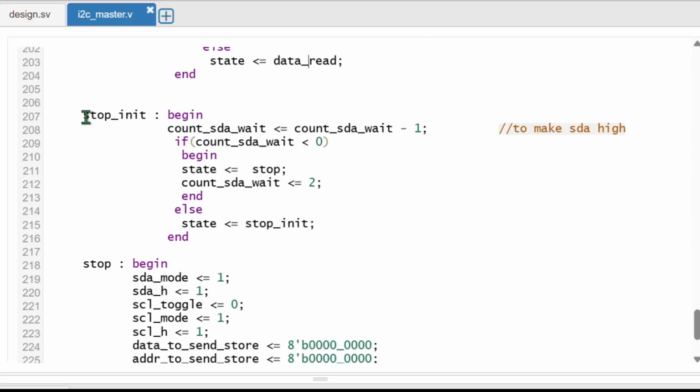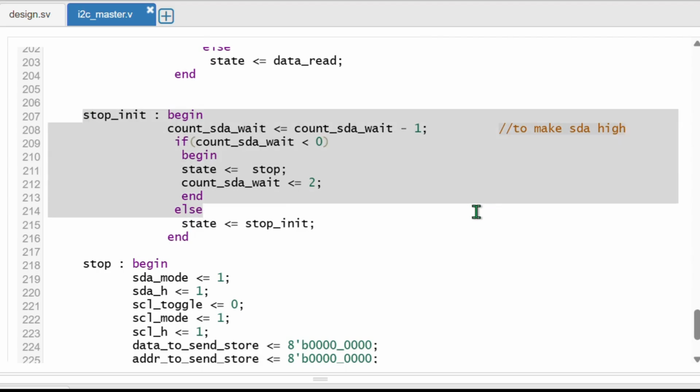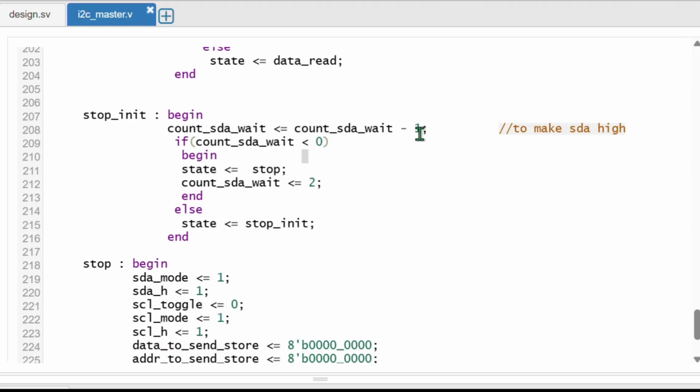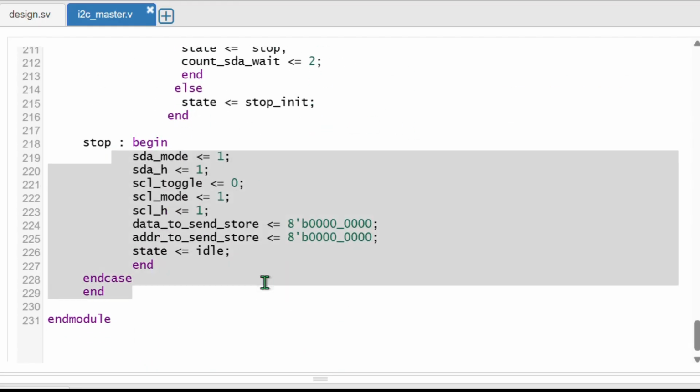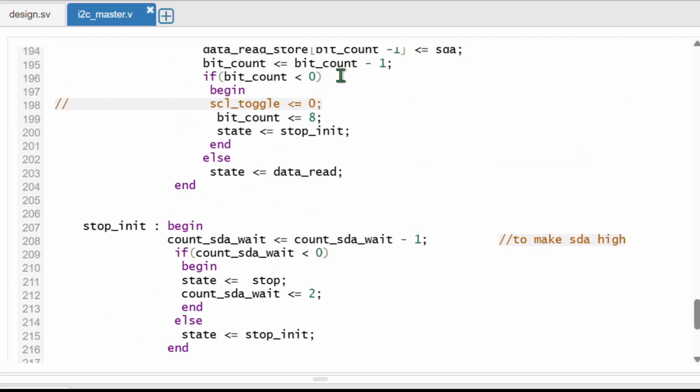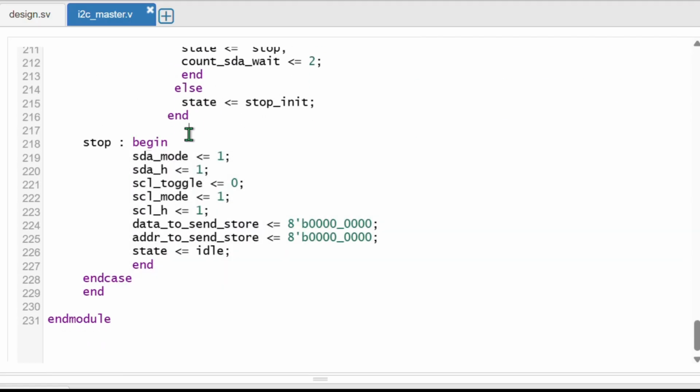We will stop that. Okay, master has sent all the needed things to slave, and we will stop here. So we have to wait for the acknowledgement for data from the slave, that okay, stop. So we will stop. Now low to high is our condition for stop. The signal will be low because we are transferring data, then it will go to high. We stop. This mode we have to ignore, but this mode is low to high, means standard mode, 1 mode.